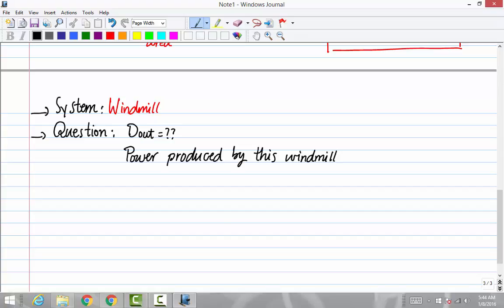Imagine that you hold your hands around your eyes like a camera lens, and you're looking at somewhere, and people are passing by, or there's wind or cars or whatever. So this is the flow, but you don't move your head. You are just looking straight in front of you. This is called control volume because the volume is the same and the mass is going through the system.